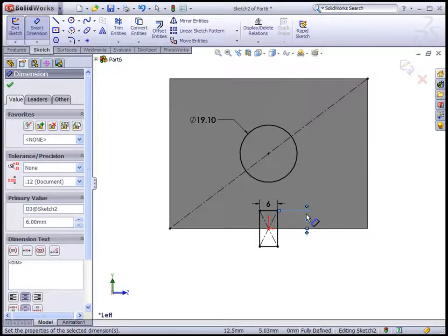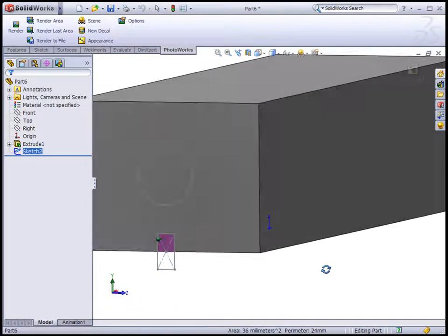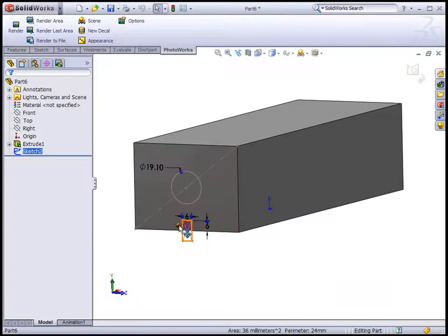Once we've created our sketch, we can then tell SolidWorks how far to cut into the model. First, we'll extend the bottom slot so it runs all the way through the model. Then we'll drag the CO2 canister hole to a depth of 52 millimeters. So now we have a perfectly sized block to begin our design, but what is its mass?